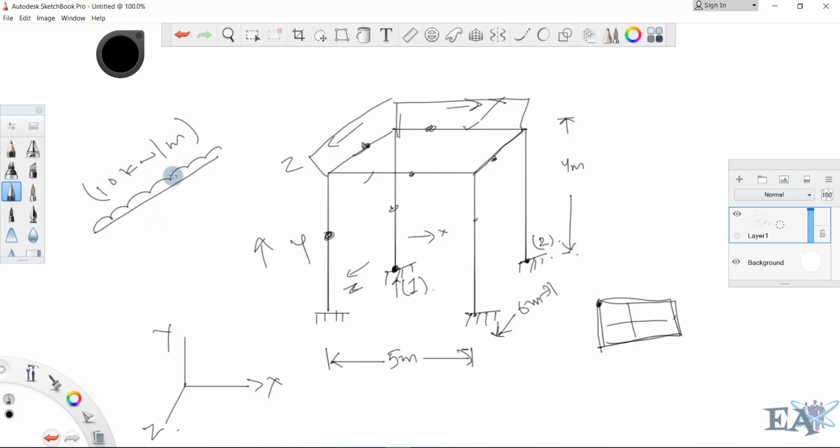While doing building, we will see how this load intensity can be calculated. For now, let us just assume this value. This is the dead load that we are going to apply. Let us apply 10 kilonewton per meter load in these two beams. These two beams will have 10 kilonewton per meter load, and in these two beams will have 5 kilonewton per meter load. Okay, now let us define accordingly.